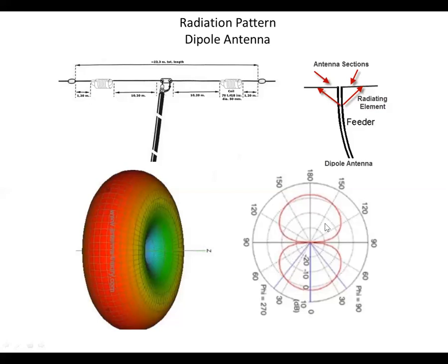There's a lot of modeling software that you can use to model antennas and see the so-called propagation pattern. But the thing to keep in mind is that's theoretical, and it may not actually look like that. There'll probably be some slight modification when it gets in the real world. The easiest one to see is this dipole, where it's actually more omnidirectional than having these nulls here on the wire plane. So that's kind of what the radiation pattern looks like.